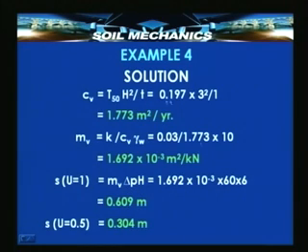So, we know the total settlement in this case from these values of mv, delta p and H, because delta p is known as 60 kilonewtons per meter square, and this gives us 0.609 meters as the total settlement. So, the settlement corresponding to 50% consolidation which takes place in 1 year's time will be 0.304, because 100% consolidation corresponds to 0.609 meters, therefore 50% consolidation would correspond to half the settlement, that is 0.304 meters.